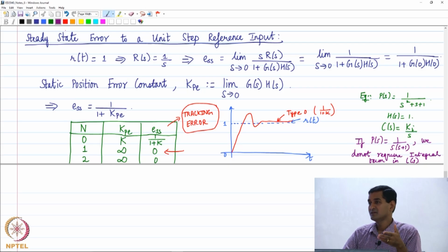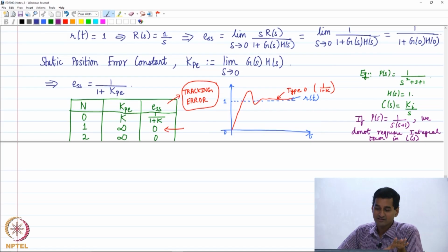other analysis, that purposefully introducing a pole at the origin has a counteracting effect. Okay, nothing comes free. So, if we introduce a 1 by s term through our integral term for this purpose, I am going to have an open loop pole at the origin, then stabilizing the closed loop system and getting closed loop performance are going to be relatively more challenging. So, there is a price to pay, alright. So, the control design needs to be done more carefully, fine.